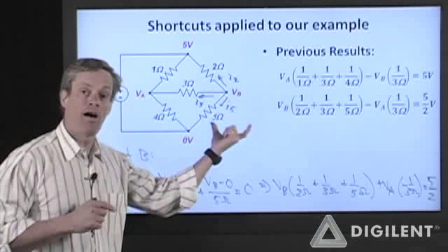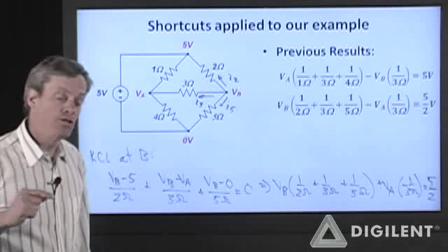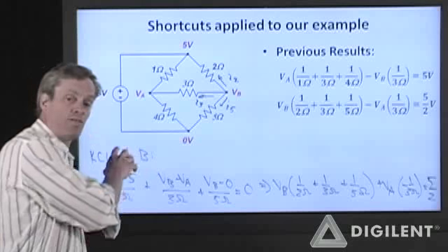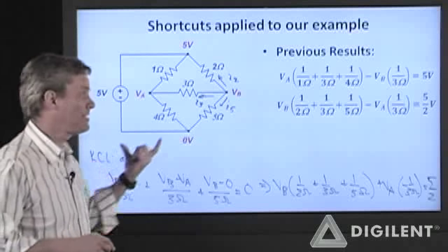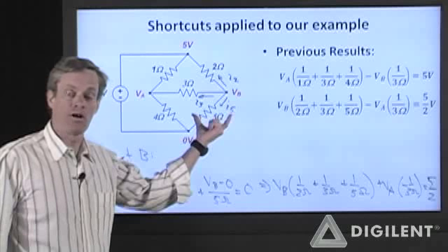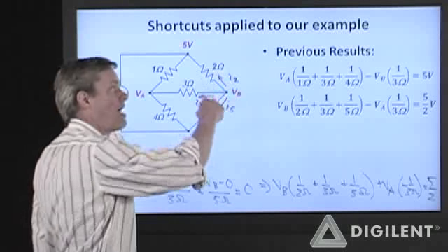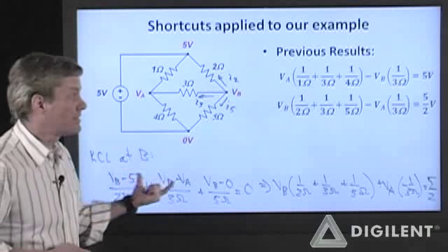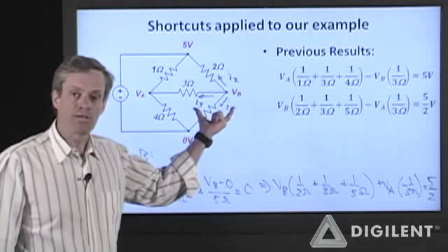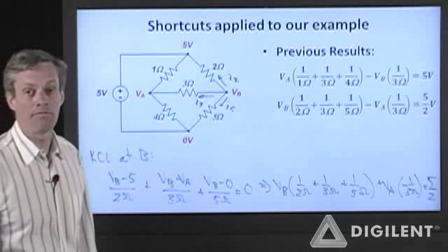Okay, the signs have offset themselves. Everything's back to being hunky-dory. As long as you're consistent about your assumptions within every application of KCL, you're okay assuming that all of the currents are leaving any given node. And in general, since I know I'm going to be making this assumption, I won't even label these currents when I'm writing KCL. It saves me a lot of time.